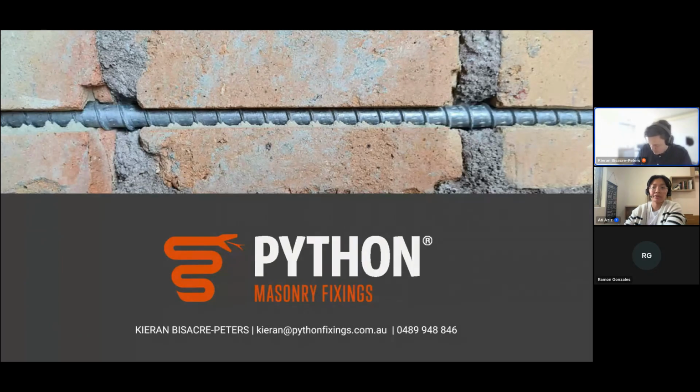Good questions. So Python fixings are made from high strength steel, about 1,000 MPa yield stress. The reason for that versus them being stainless is because of applications, for example, your shotcrete overlays and composite action between 2 layers of masonry. It's really advantageous to have high strength steel in those situations. So you can use fewer anchors across the project and keep the cost down. These projects are always cost sensitive. Stainless is also very expensive.